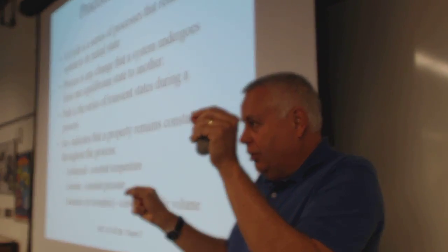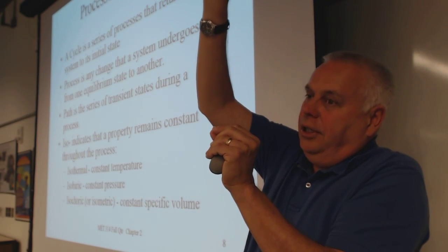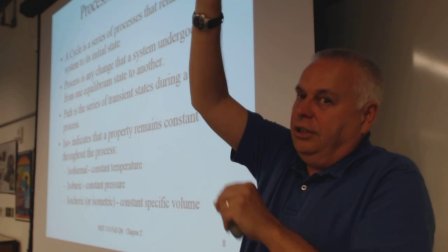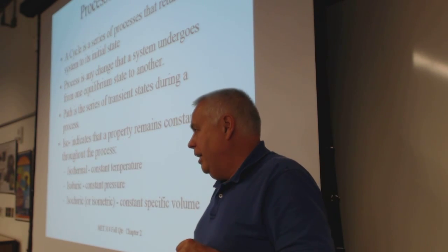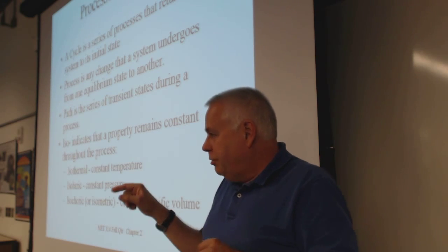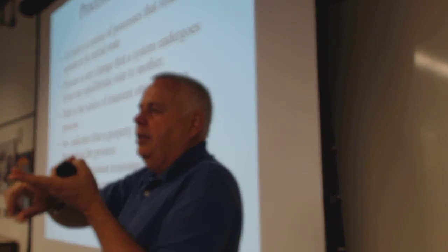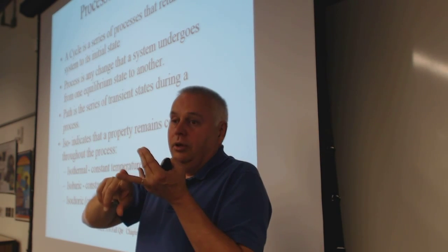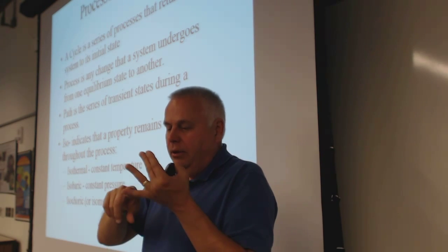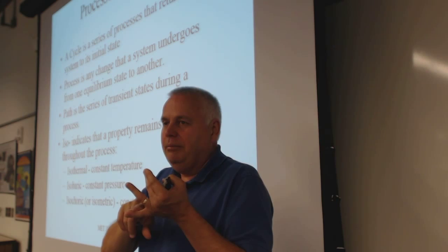So we had an isentropic compression, a constant volume combustion, and then an isentropic expansion, and then back down to where we started. Those processes will be defined in terms of basically same temperature, or same pressure, or same volume, or same entropy, which we need to get through entropy before we talk about what that means.